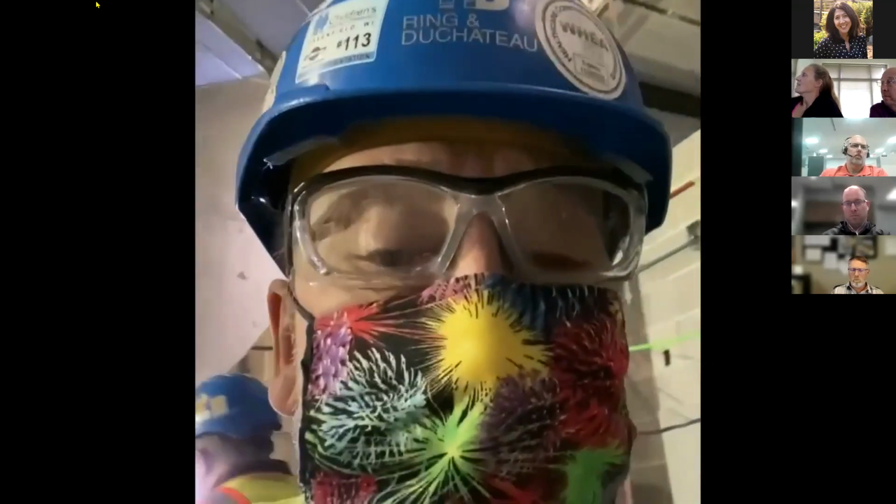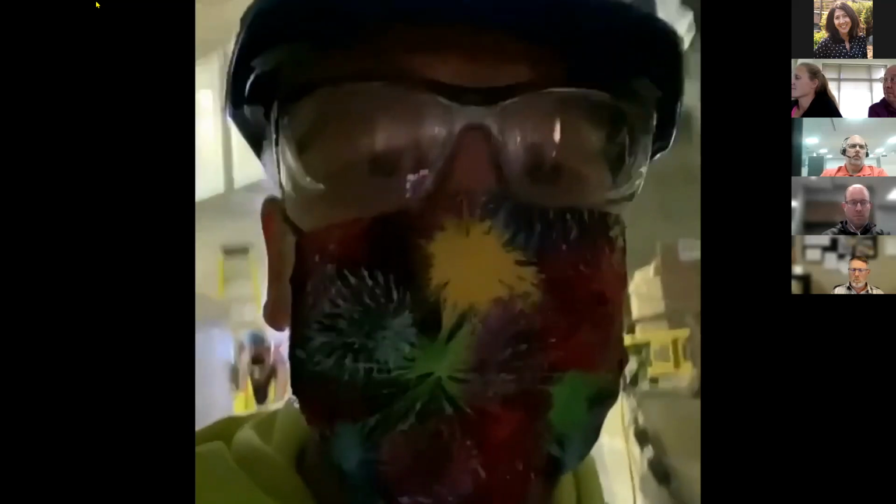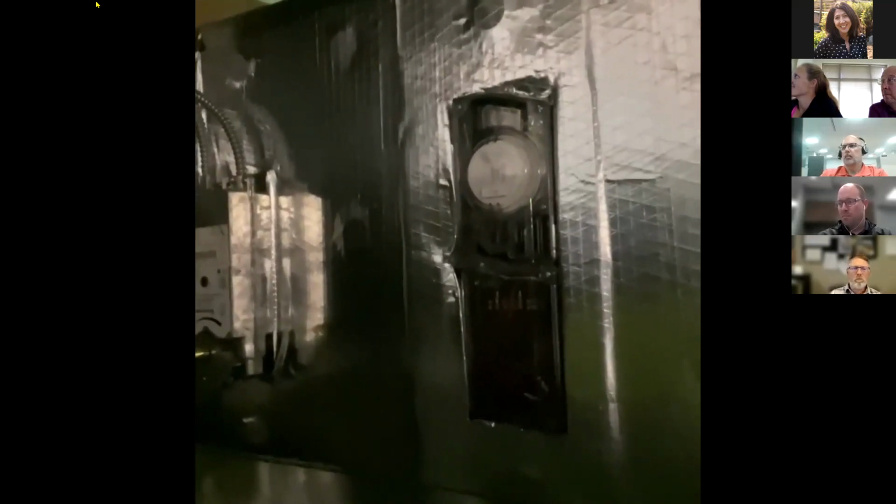So we took the test switch out of here at the fire alarm, but now it actually has to get reset at the fire alarm panel because it was actually a trouble. So our lights should come back here. Our duct detector is blinking safety green. Our safety module hasn't released quite yet. And there it goes. Come back up. We're good to go.